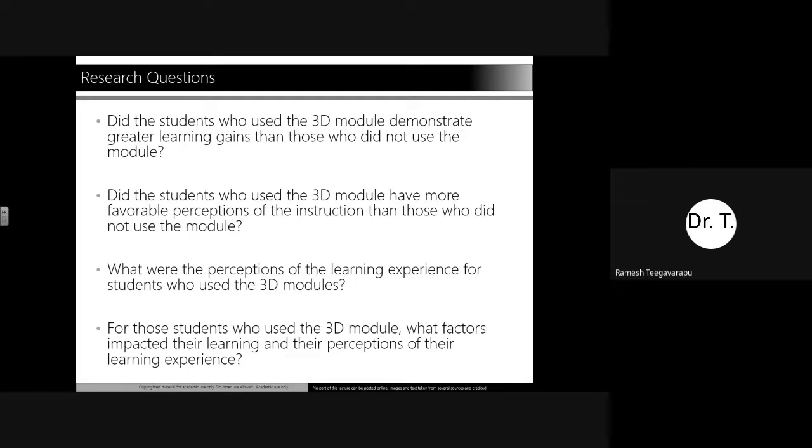Now let us expose you to the 3D environment, and see how your understanding has improved in terms of structural flood control, changing the sluice gate heights, opening them, changing the levee height, changing the hydrographs, how the water levels change as the hydrograph moves, and how the inundation extent is increasing.